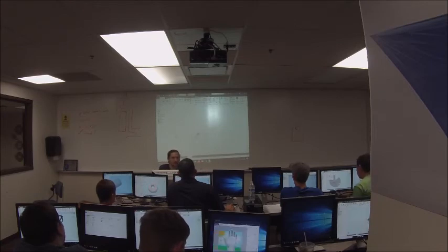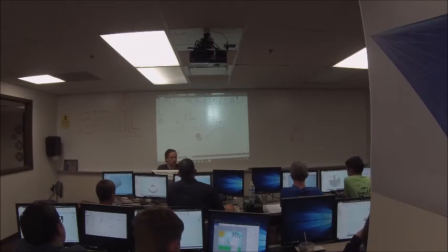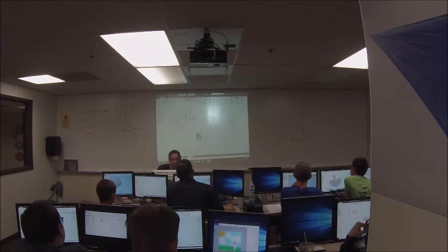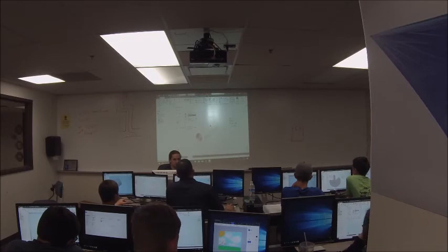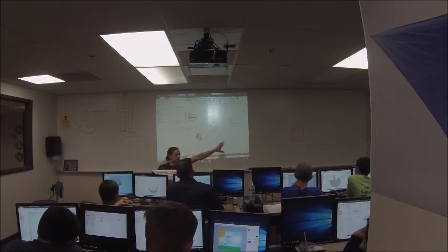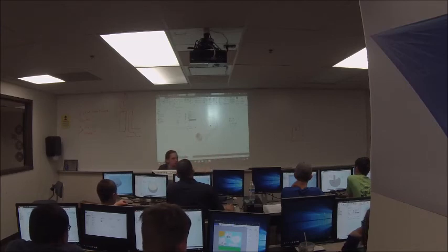So I can edit my extrusion here, and I can click here where it says extents. You have this box where you type in, and there's also this box out here, it's the same thing. I don't remember what this little widget is called, but you can do everything you can do here in this window, it's either or. I typically use this one, but for the class it's easier to see if I use this. So you can go up here where it says extents, the little drop down box. It says distance. You can select another face, and it'll extrude up to that. The one that we want is all the way down at the bottom. It says all.